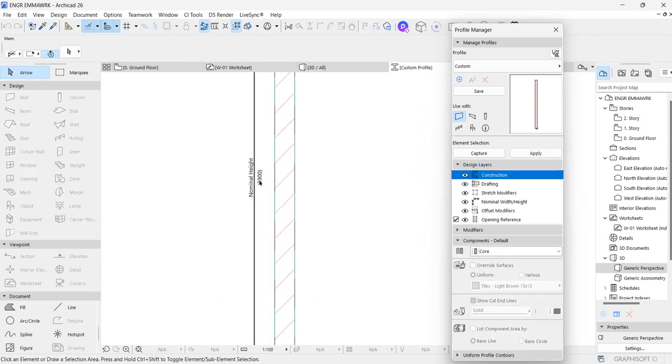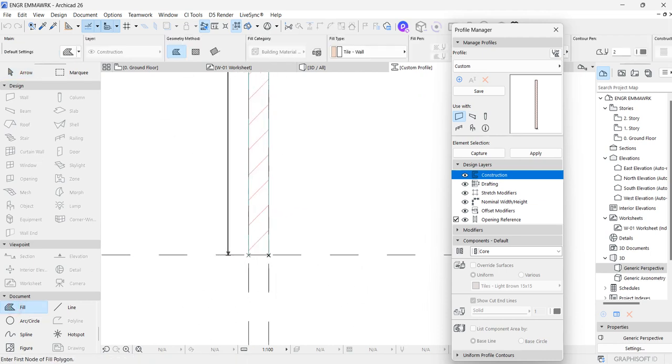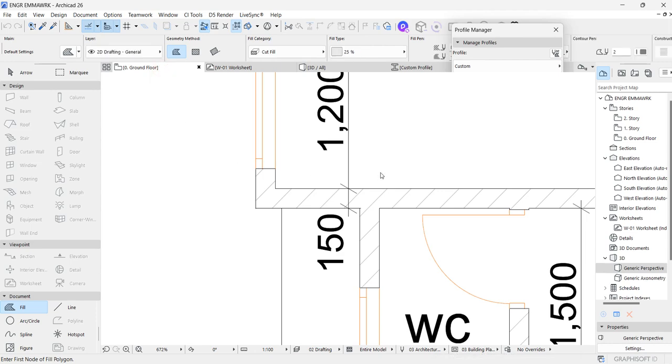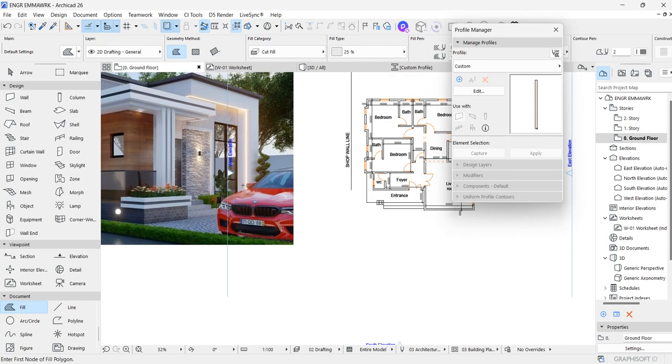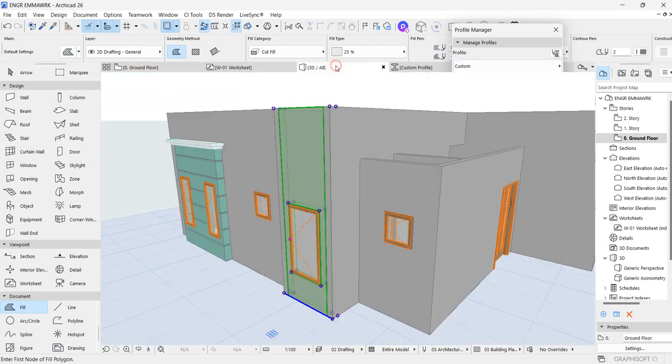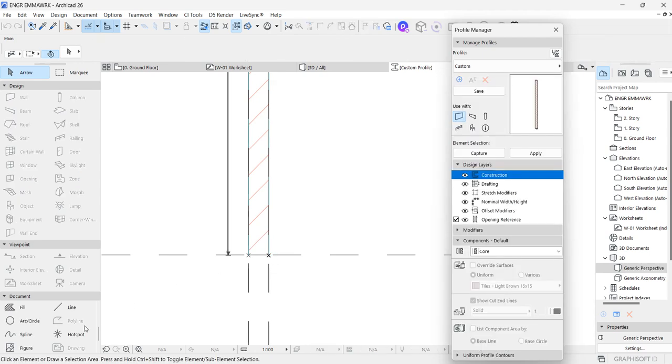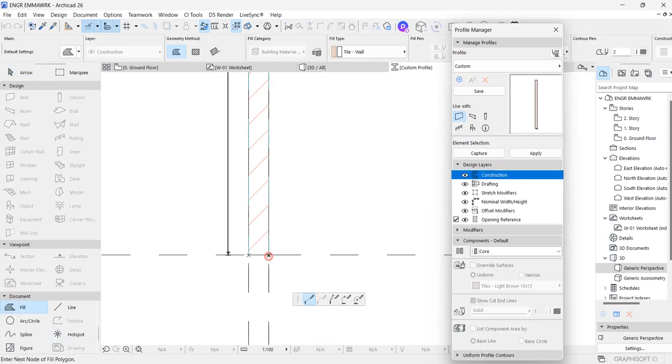Okay, so you can see the wall height 2.9. Let's check the design of that wall again. It started from the ground. Okay, so we have a DPC of 450. So let's say 450 down. Oh no, 450 down. Let me choose. I'm using fill 2, 450 down.